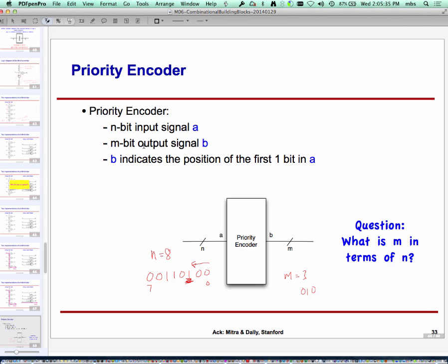Or let's take another example. Let's say we look at the left digit in the top segment. The left digit of the top segment is displaying the tenths digit of the temperature, which in our case is 6, 7, or 8. So it's always lit up, except when either the set point or the temperature is invalid. So the condition in this case will become: top left segment is lit up, except when either one of the two is all zeros, either or both of them.